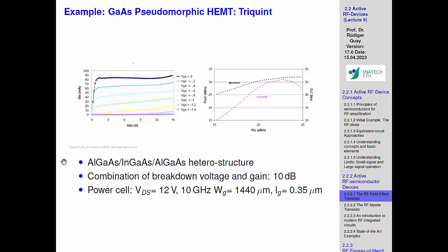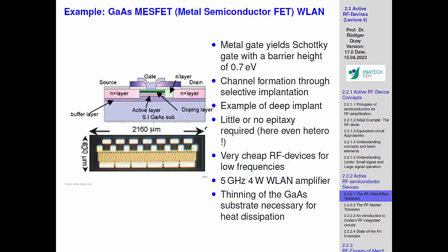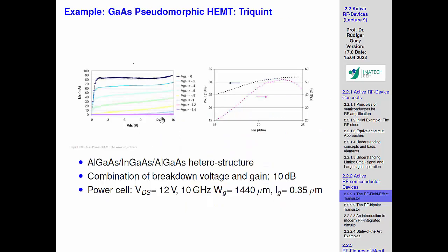And what does that have to do with this plot? The plot is that we still have very small devices here in this regime to make them fast, but at the same time, we're also using this principle that we make relatively big transistors. Yeah? And here you can see that we have three advantages. The device has not a small gate, but a reasonable gate, and it has a voltage capability of 15 volts here. Yeah? And then you see that such a transistor, even around 10 gigahertz, where we do some of this stuff, so the satellite communication, they're using this frequency, maybe 14 gigahertz, and the base station connections are then going up to, let's say, 30 gigahertz.